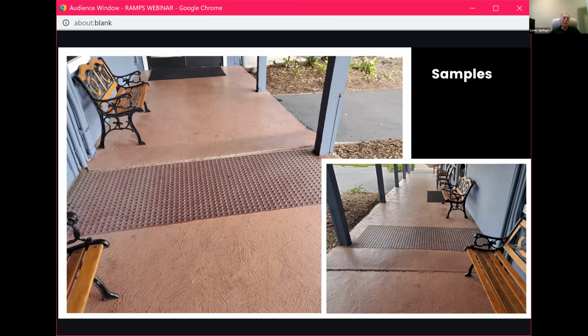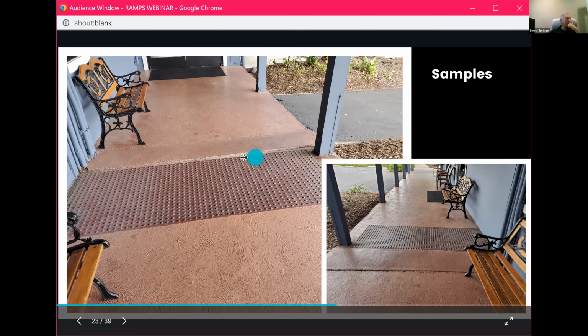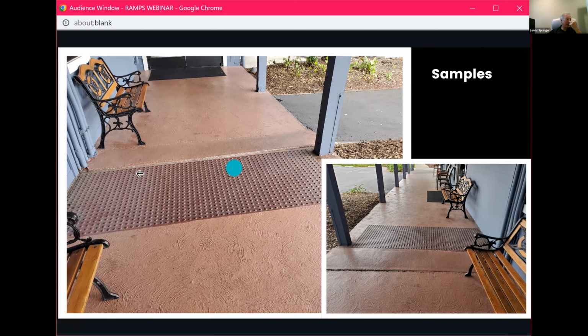Then as I continued along this path, I came across this detectable warning, which, as you can see, is just in the middle of a walkway. It's just a walkway. And there was this little chunk of concrete right here, if you want to point it out, that has lips on both ends and slopes about 1 to 10. I don't know if the detectable warning is to warn somebody that they're about to trip, but it certainly doesn't belong here.